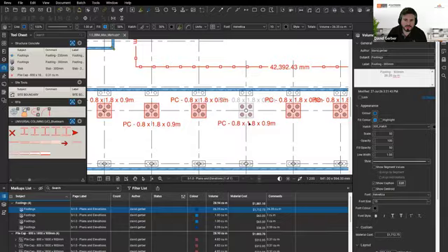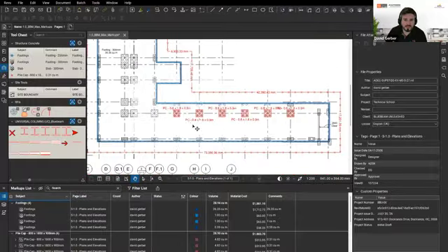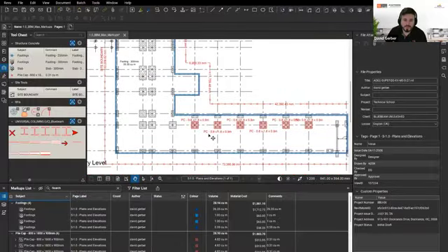And then I could just hold shift to bring my labels down if I want to clean that up a little bit. So very quickly, converting stuff, duplicating stuff, offsetting stuff, thinking about groups, scaling your stuff so that it's always accurate. So relatively quickly, I can smash that through. And I like to use layers, I guess my AutoCAD mind, I just hide stuff and see stuff that I need. So then I can even go further with organizing my documents.